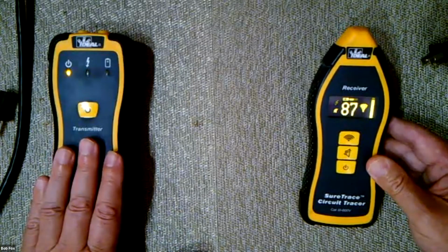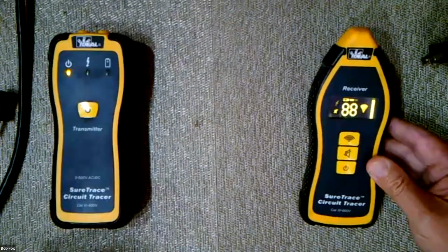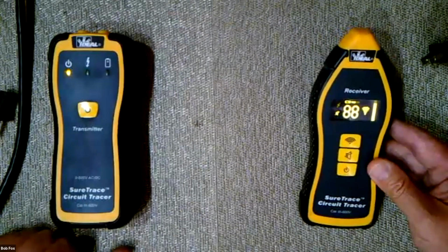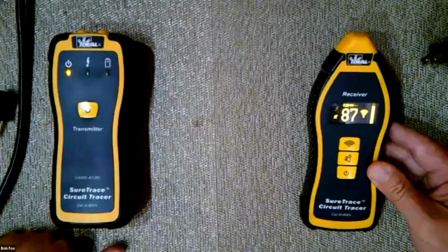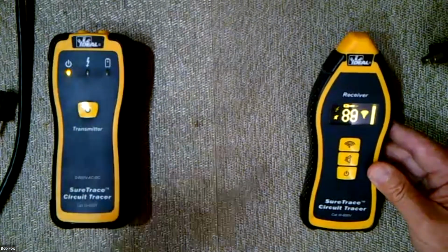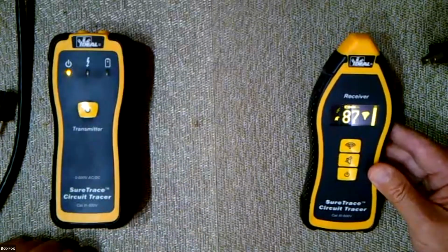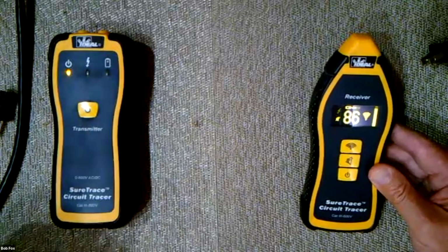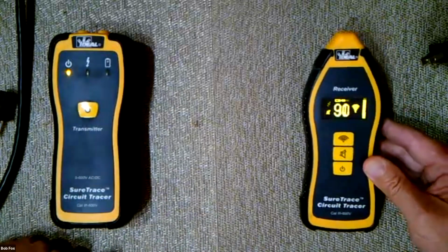We've sold these to plumbers to locate copper pipe, doorbell or alarm wire, anything that's electrically conductive. Fish tape: you can jam fish tape down an empty PVC conduit and loop it back with another wire so you have a complete loop, send the signal down, and find out where the end of the buried PVC is, so you know where to dig it up to continue repairs or an installation. We've seen that happen in times gone by.